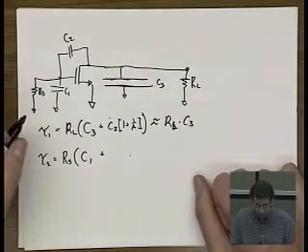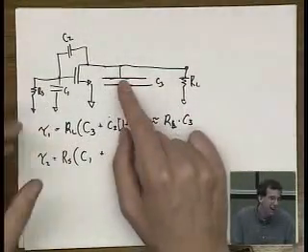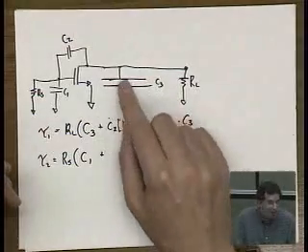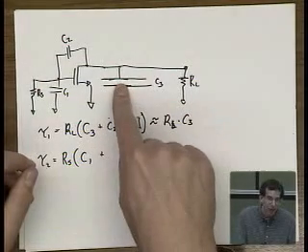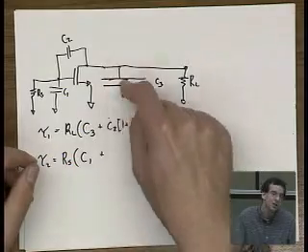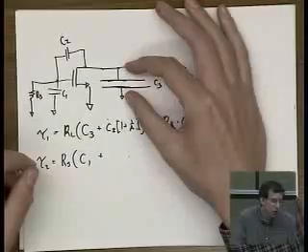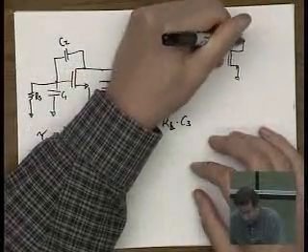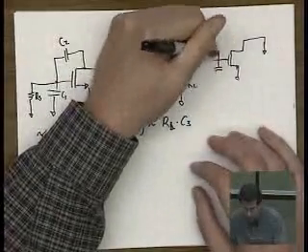No, it doesn't. And the reason why is because if you look here, this capacitor gets Millerized, but to a much lesser extent. And this was the assumption I was talking about before. This capacitor kills the gain here because at frequency it looks like a very low impedance node. As you go higher in frequency to find the secondary pole, this is going to look like a really low impedance node. So in the limit, the capacitor now just looks like a short. And so now you have this.